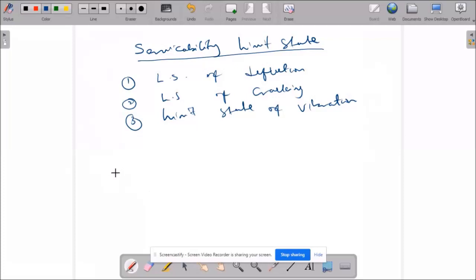The serviceability limit state is not a physical situation, but rather a computational check. The load and the resistance factors are determined using statistics and a pre-selected probability of failure. Variability in the quality of the construction and consistency of the constructional materials are also accounted for in factoring the loads.